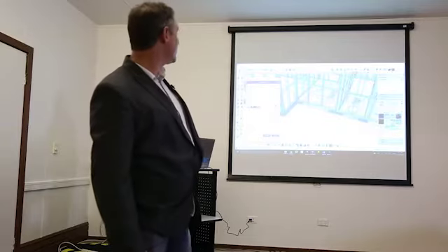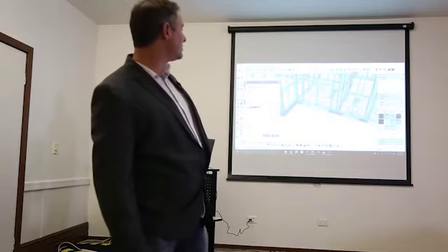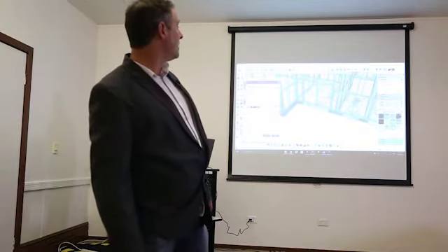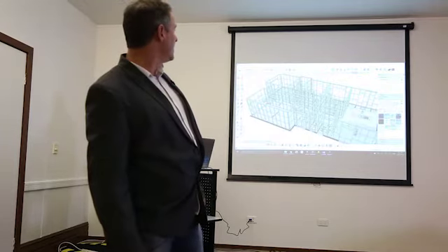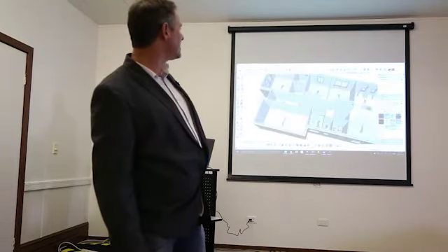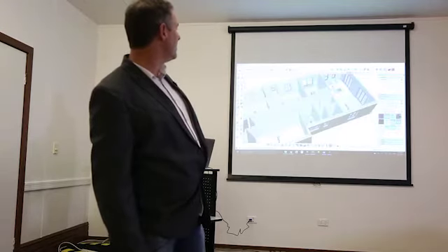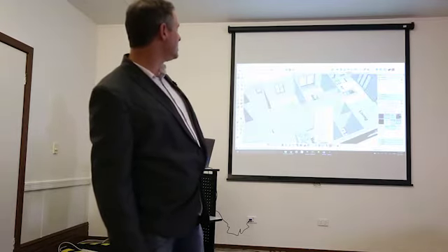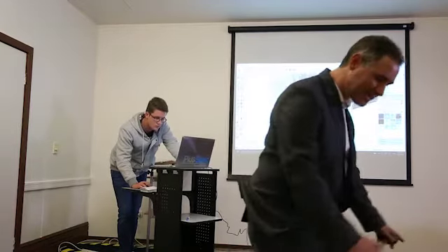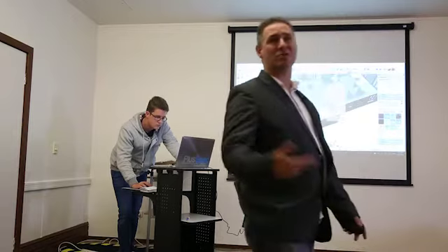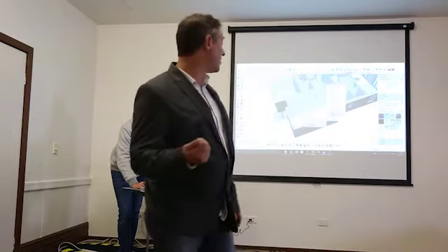All right? So, Grant, I probably wouldn't put every window in there because we don't want to bore people here. Let's maybe just put some internal doors in and put a roof on it, maybe a slab with a drop edge beam of 86 mil. Sorry, just an edge beam. So everyone would probably know if you're building on a concrete slab, you have a flat slab and you have a step down of 86 or 172 according to suit the brickwork.